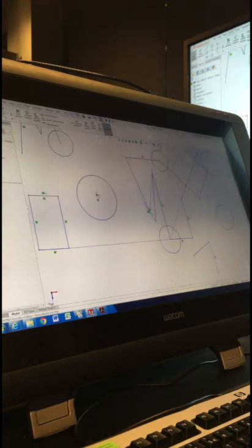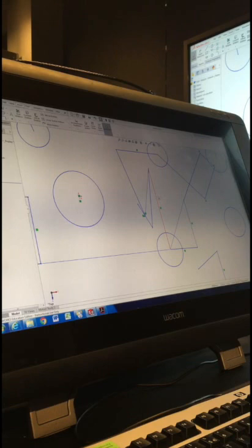Now, last thing I want to touch on in this before I clear it and we start the first part. Can anyone notice in their sketch lines that look a little bit different? Okay, different in thickness. Yep. So that'll happen when you have line segments which create an enclosed space, and then another line segment which is almost like it shouldn't be there, right? So if we look at this shape here, I've got an outline going around this part, and then I've got another line that's in the middle of this section. I've got another thin line here as well.